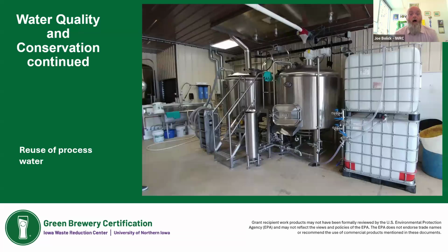reusing it there. Another thing that we've seen, which this is a picture of, is creating a closed loop system for the heat exchange. So this particular brewery, they had a handful of tanks and a pallet jack where they would put one of these totes into their cooler where they had some extra space, with ambient temp water in there. It would cool down. They would run that through the heat exchange unit, which would then actually drop the temperature quicker because they were using colder water than just tap water, because it was in their cooler.